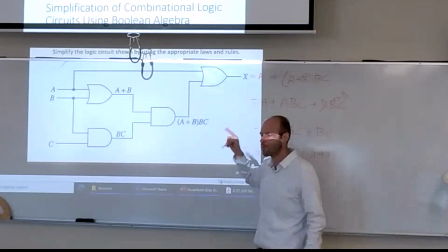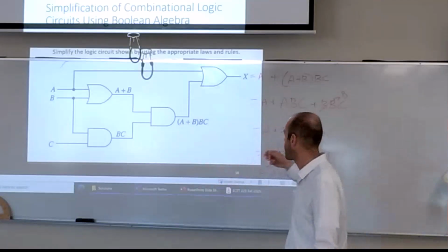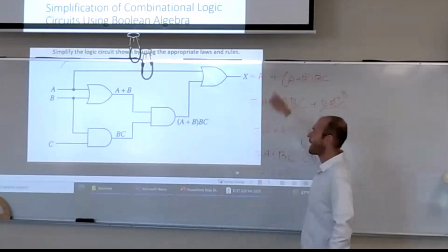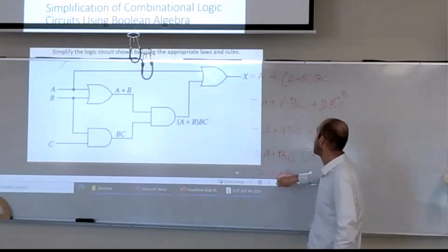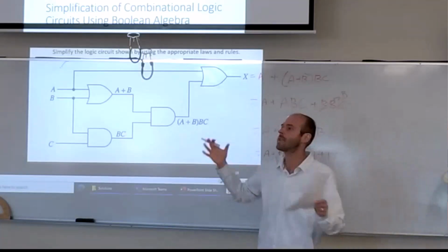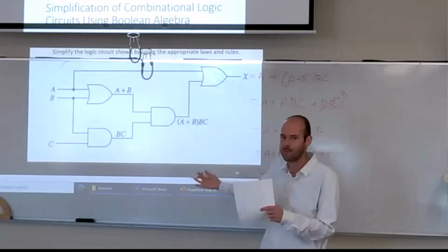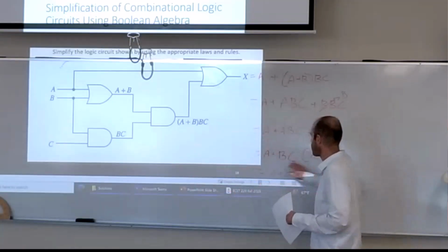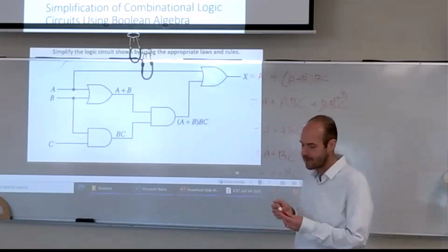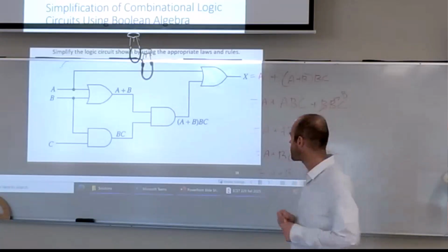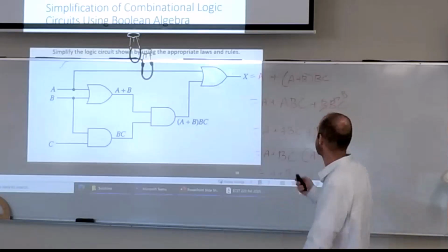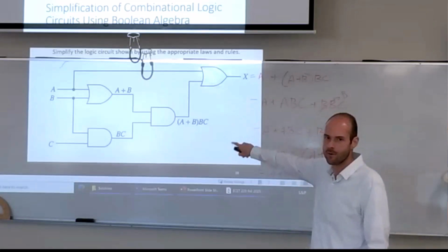So we're not showing it right now, but we will in some of our lab examples. If we made a truth table for X out of these 2 circuits, they're identical after going through the simplification process. The reason that it works like that is by eliminating things, we're just eliminating redundant logic that would have resolved to the same thing. We've cut our number of gates in half, which means you've cut your cost potentially significantly. And you've made your boss at whatever circuit design company you're at very pleased with this work you've done. So any questions on that process before we click to the next one?